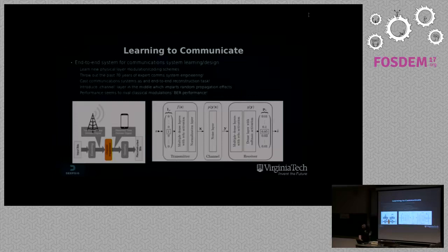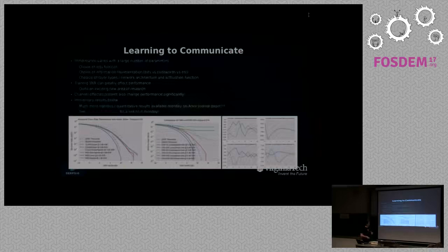So if we do that, we can start plotting basically BER curves, and these are kind of some old ones that aren't as clean, but you can see that in some cases we can outperform the performance you would get on a modulation without any error correction, which is really cool because it means the encoders and decoders that we're learning can actually learn a little bit of error correction as well. So you're basically learning something that does better than just a normal modulation scheme.